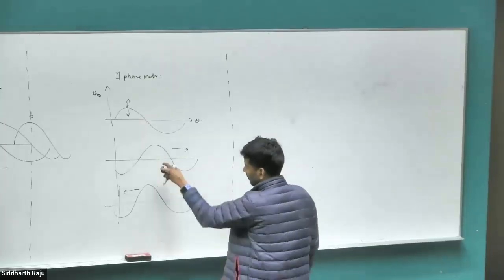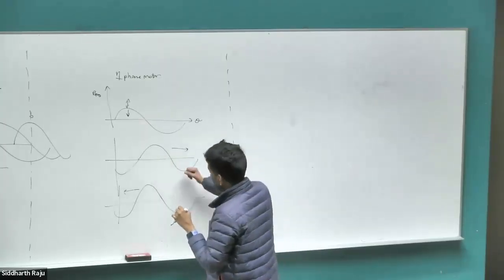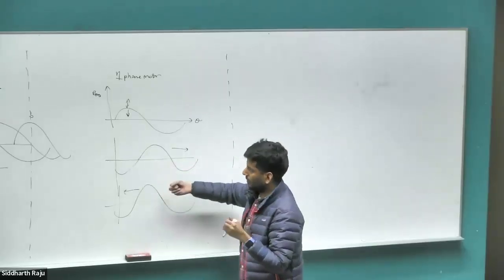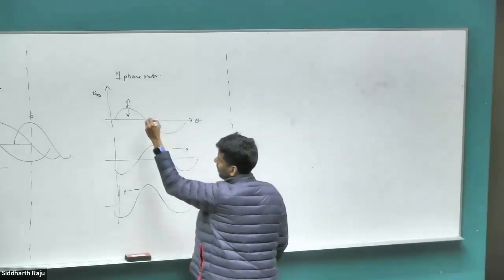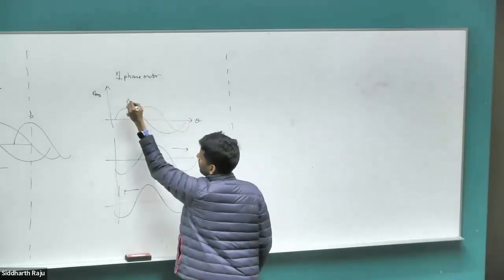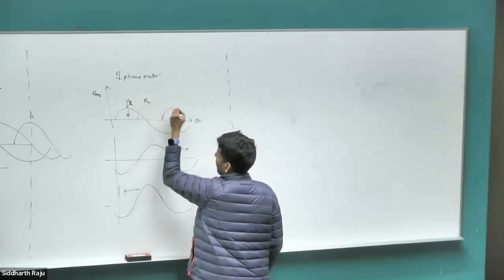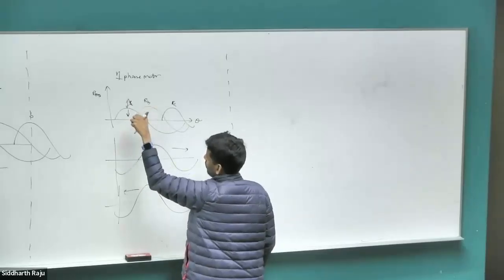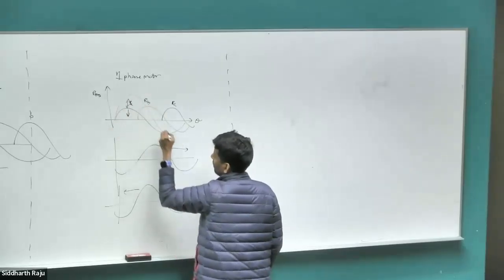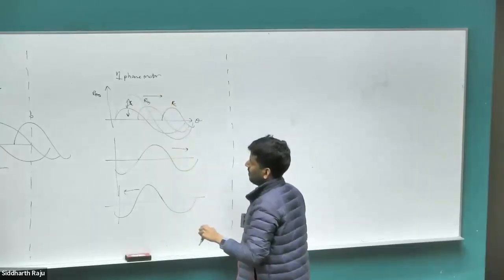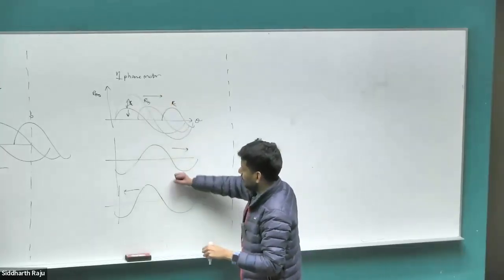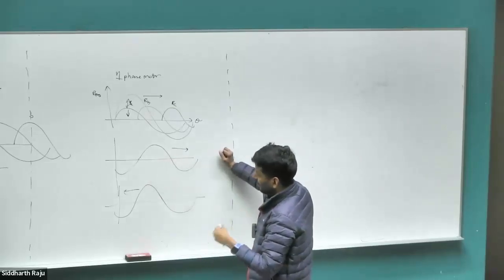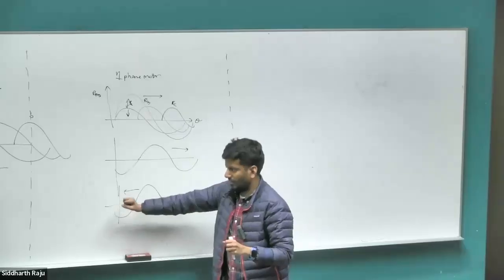If you look at just a forward traveling wave alone, this is the same as what we would have gotten for a three-phase motor. Absolutely exactly the same. In case of a three-phase motor, the three individual BA, BB, and BC, which had different magnitudes at the same time, interacted to create one single forward traveling wave, which was going in this direction. So when we decompose this into two, we can think of it as one three-phase motor, which is creating a forward traveling wave, and another three-phase motor, which is creating a reverse traveling wave.